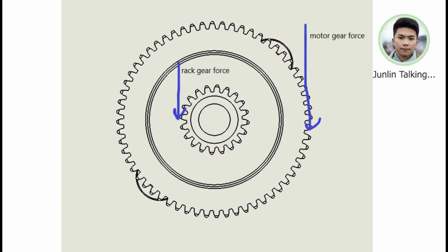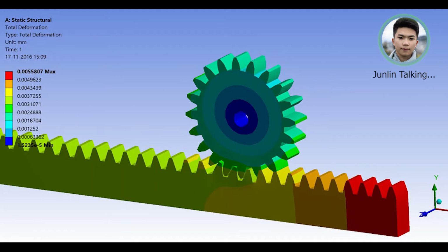I will be talking about the stress analysis done for our project. The stress analysis in our design will focus on the stress on gears, as it is the most vulnerable part in our design. Two aspects are important when considering a stress analysis on a gear. The first being tooth breakage that could happen with bending stress, and the second is surface pitting that happens from excessive contact stress. In both cases, it is most important to analyze tooth force that is delivered from the torque. We will be using the bending stress method in our analysis.